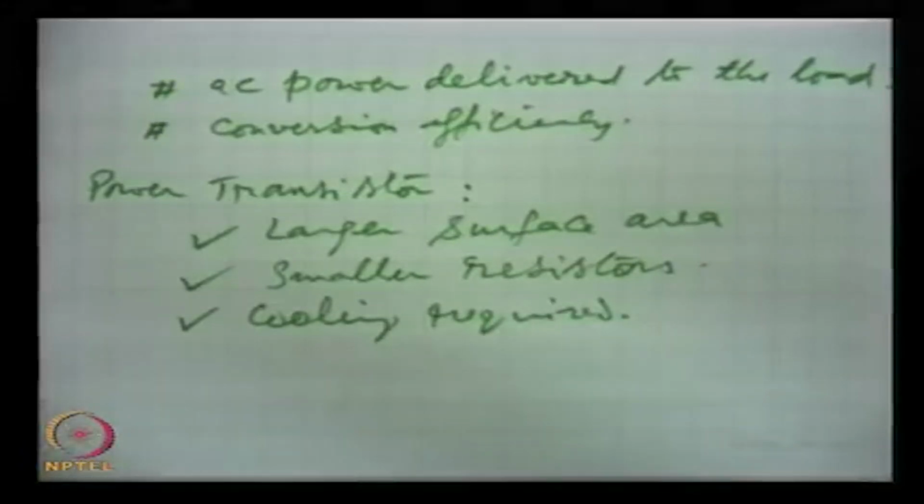For this, often you must have noticed with several instruments that there is a fan associated with the unit itself. So, that fan cools the transistors, and if this is not that high power, then instead of using a fan, many times the transistors, first thing is that transistors have a metal casing, so that heat can be dissipated through metal more conveniently and more efficiently as compared to plastic bodies.